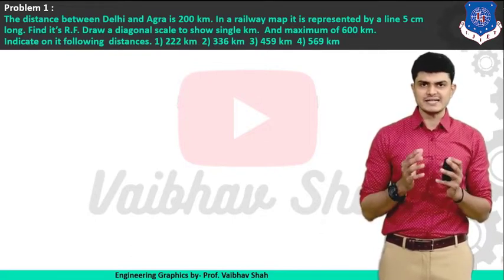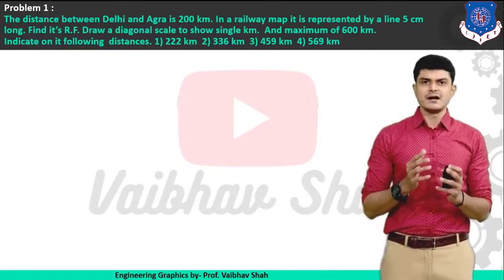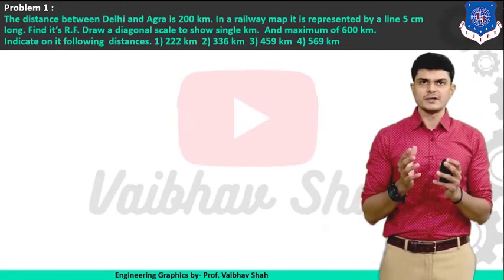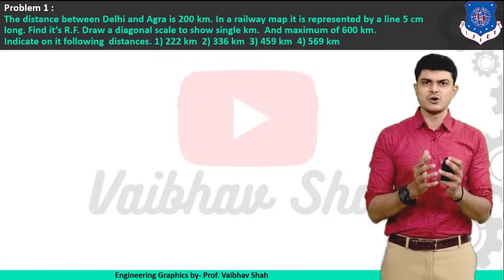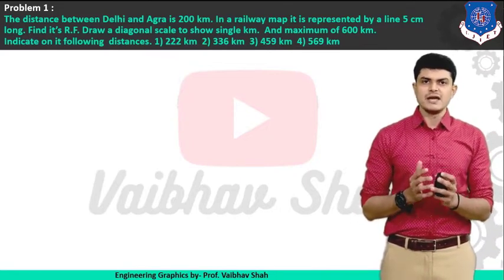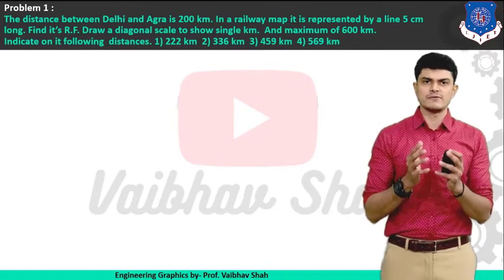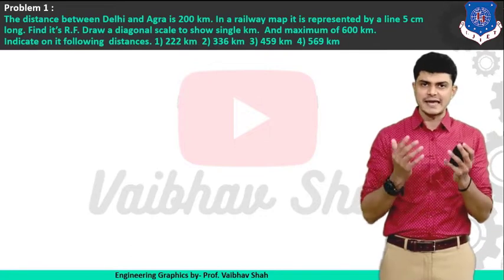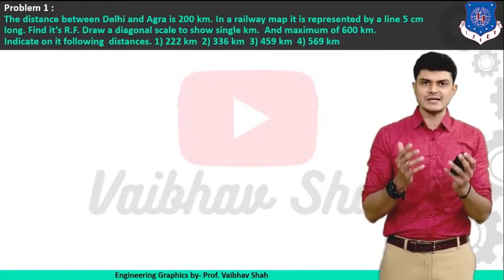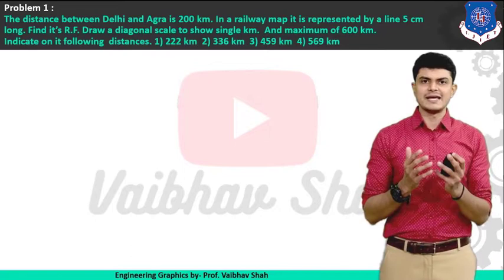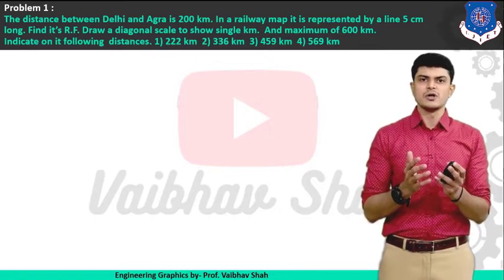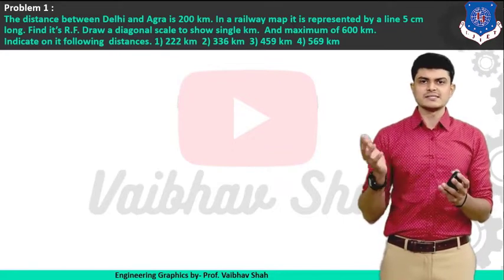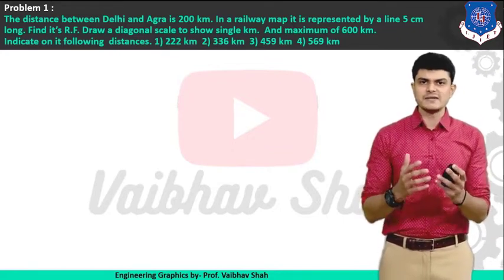569 kilometers. Let us first start this example by understanding its statement. Here, the distance is 200 km, which is shown by a 5 cm long line, which means a scale is given. And we need to use this scale to find out our RF. After finding the RF, we will use our second equation, the actual length of scale equation, to find out the length of the scale which we are going to draw on our drawing sheet. And after that, finally we will use these distances to show on our scale. So let us begin with our example.